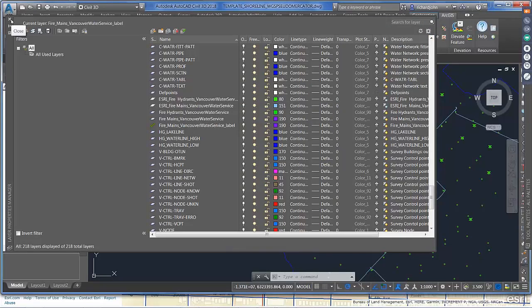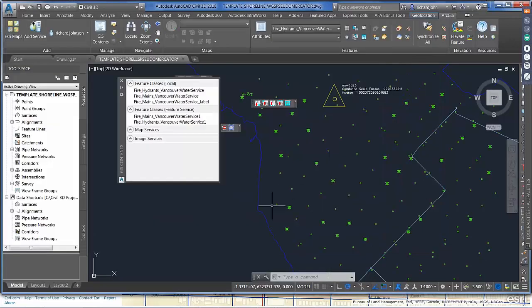So very neat, very impressive, and an easy way to ensure CAD compatibility, because we know what it's named in your GIS system. Now it's duplicating it as a layer inside of your AutoCAD system. And as a result, if you want to add anything or create anything and you put it on that layer, it's going to recognize that as an object to be updated inside of your ArcGIS system. So it manages it as equating a feature class based on properties, the easiest one is layer, to then update your Esri geodatabase with the information.